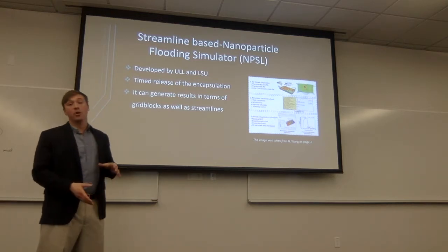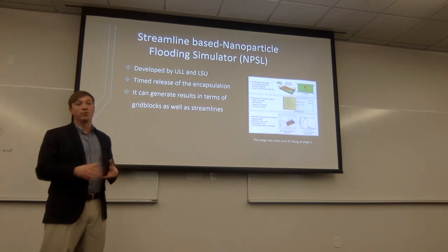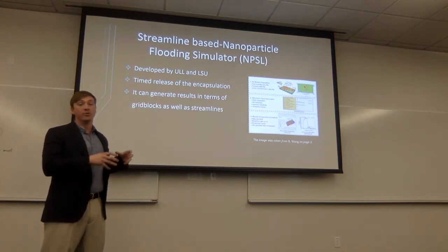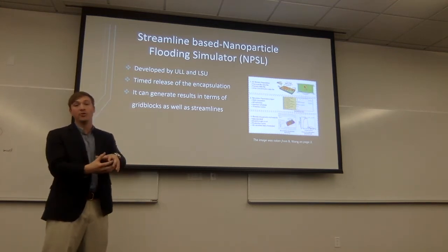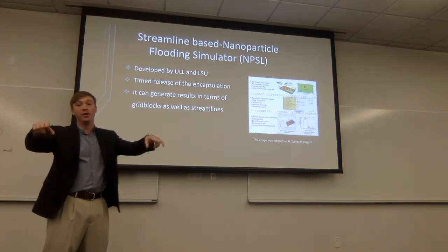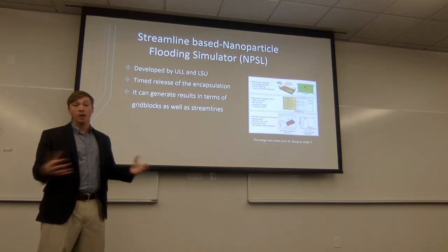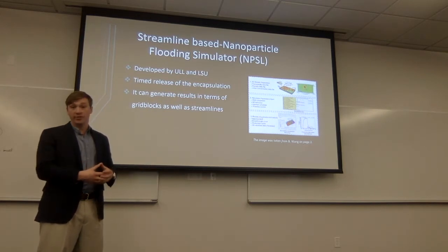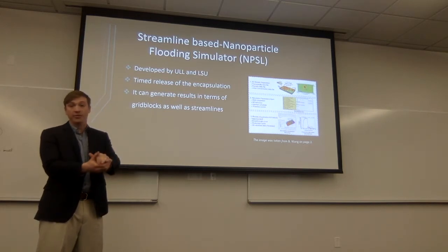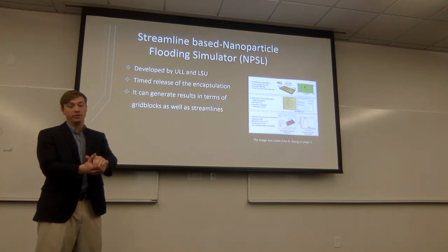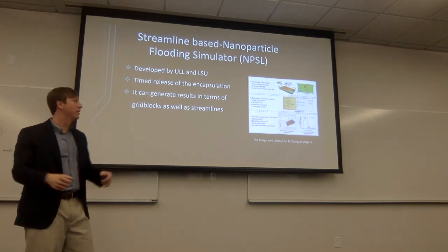And it's extremely important to our project because for conformance control, what we're looking for is a way to clog those high perm zones and force the water into the other zones. For us, that's using HPAM and chromium coming together to form a weak gel system, which forms that highly viscous fluid that clogs the formation and forces the water to the outsides.